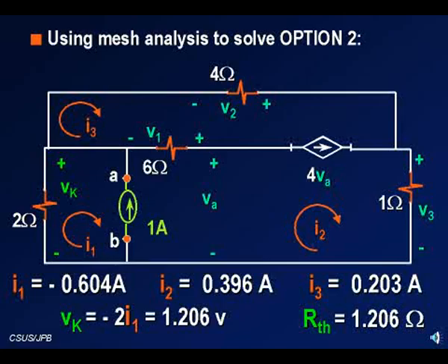In the circuit that we're doing, this is what we're going to get. Now, realize that I had turned off the current source, the 5 amp current source. That's where that VA is. So you see there's a hole there because I essentially took it out of the circuit. And then I also turn off the 8 volt source, which turned into a short circuit. And then I go back now and stick in my own 1 amp source between A and B, and my goal is to calculate the voltage Vk across it.